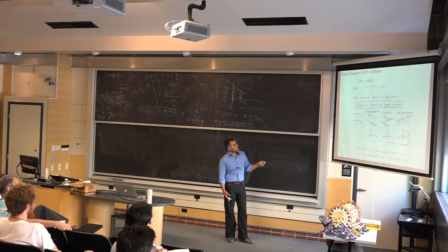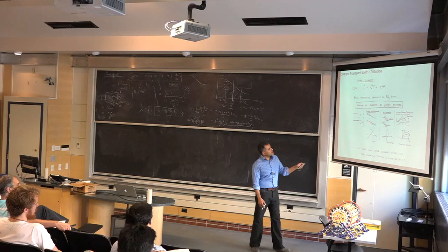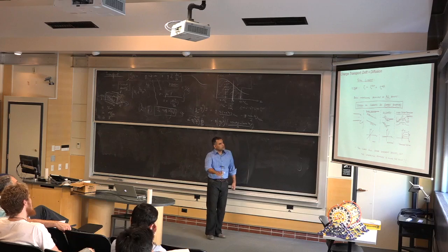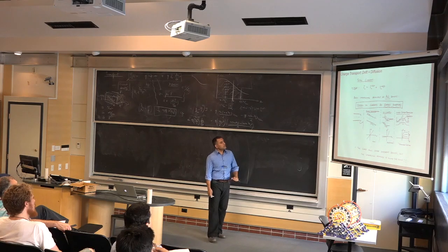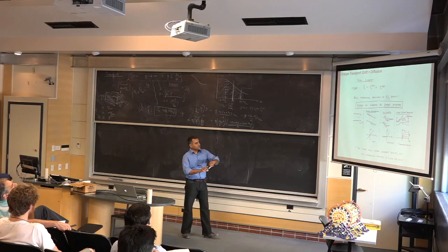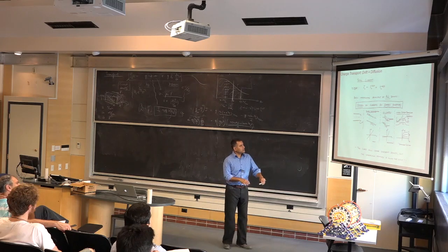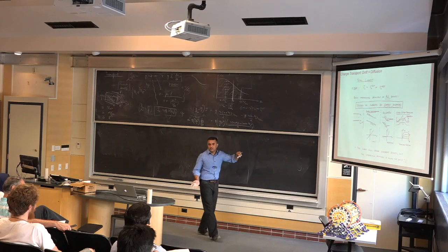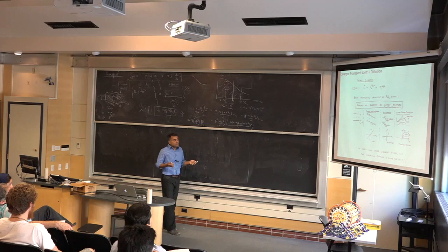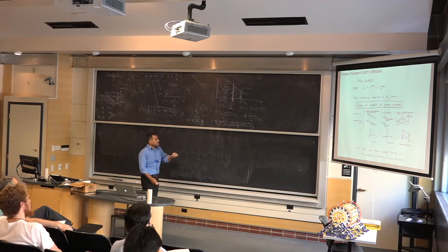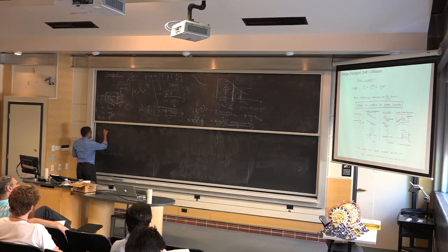And if I have bands which are filled with electrons, let's say I doped it, then the electrons can move, holes can move, and generally electrons would always want to go down in energy, and holes would want to go up in energy, just like bubbles and water. I think the good example is you have a tube and water, and you bend the tube. Water always goes to the bottom, and the air goes to the top. Right? That's the idea. Holes always go up because energetically, that's their lowest energy state.